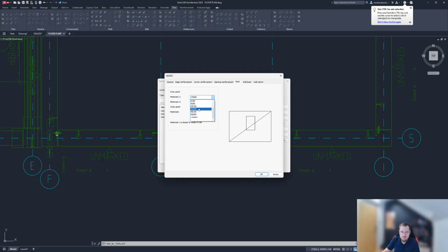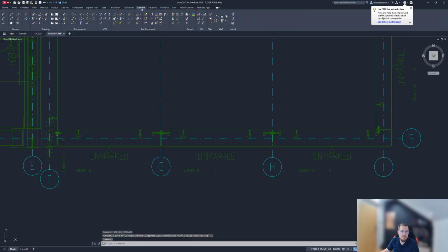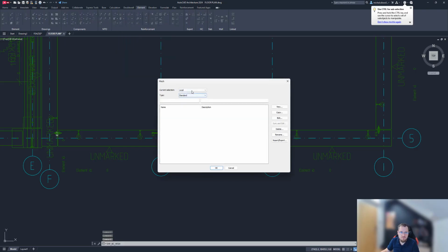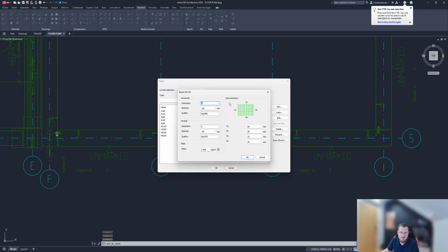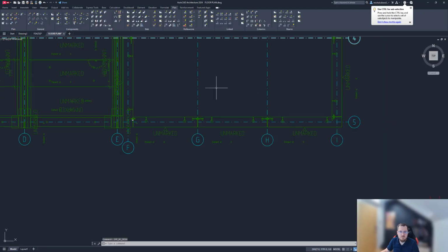So the type of rebar in the meshes, the spacing of bars between meshes, you define inside those meshes. And those meshes you define in the element and the mesh tab as well. So, for example, the one that we had before, here, you define basically the parameters of your mesh. You calculate the mass as well for impact, and that's it. That's how you go ahead and do that.